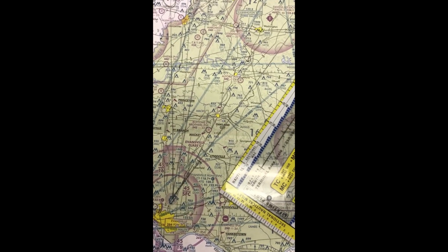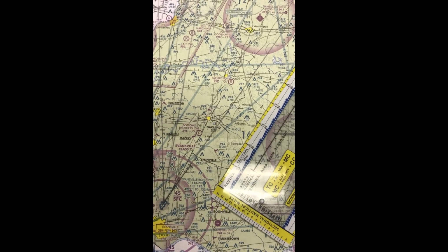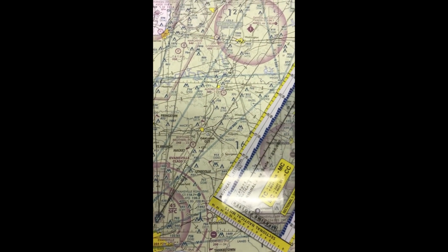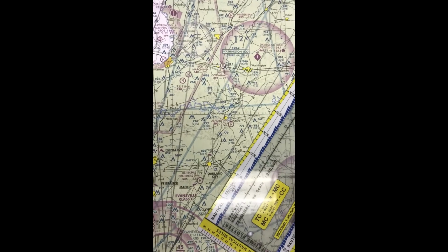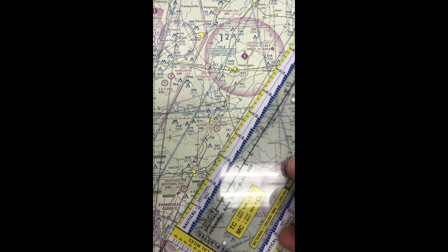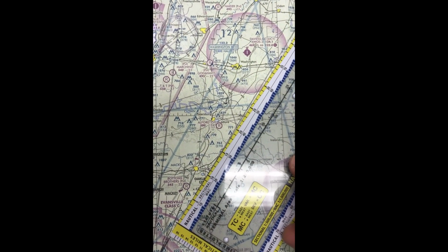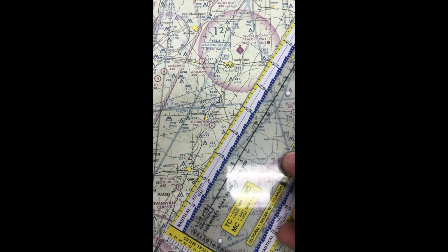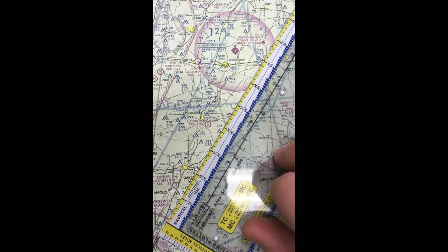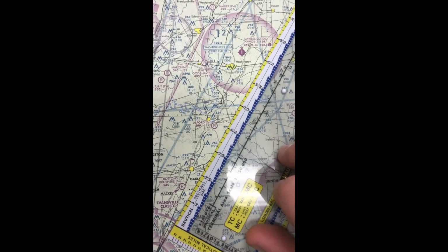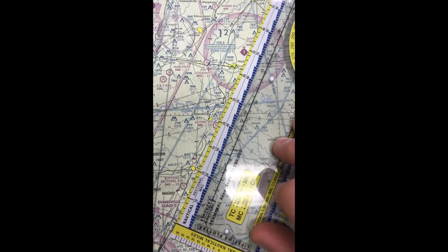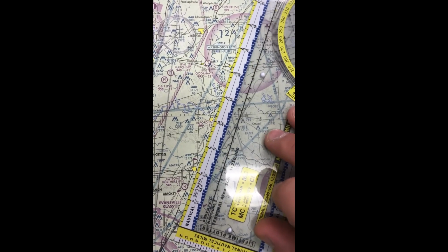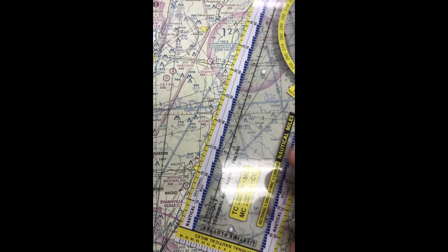We've got our top of climb point denoted on there. So the next thing we're going to want to do is start to pick prominent VFR landmarks approximately every 20 nautical miles, so we could try to keep them relatively in line. We can kind of see here that if we put that on there, we really don't have a prominent landmark at that 20 nautical mile point. So let's just go ahead and say that we're going to shift it up here towards this little town of Alfred, Indiana.